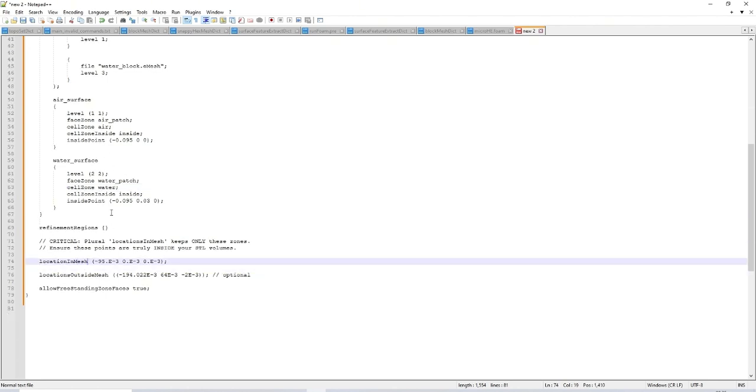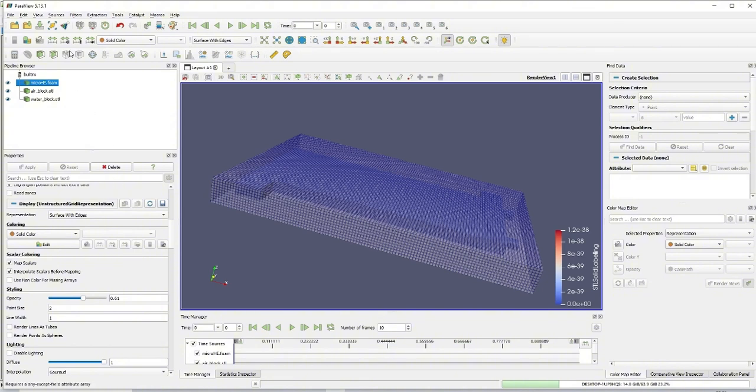So when I choose any location of this mesh, that will maintain all these two surfaces, or the two STL files, and even the background mesh will be cut out. We will see it later. So the mesh I'm going to maintain is 0.05, so that is Z at 0, 0. So I can directly have a cut of this. So if I perform a cell zone cut,